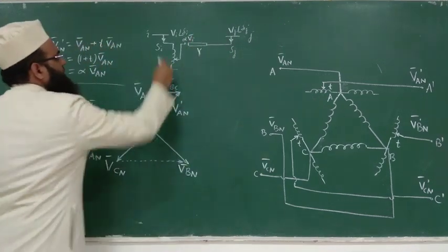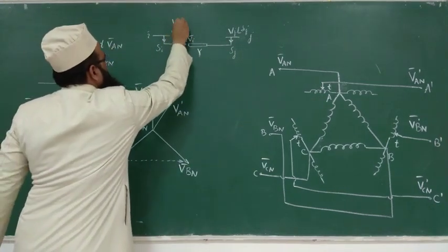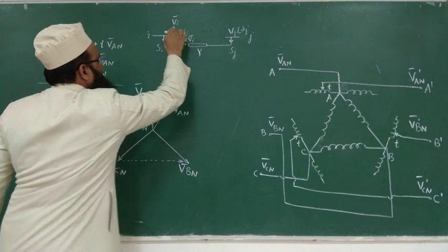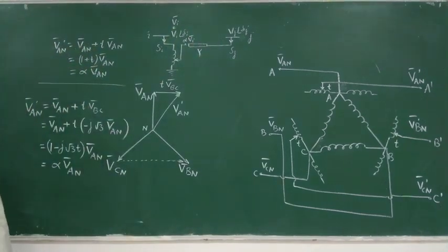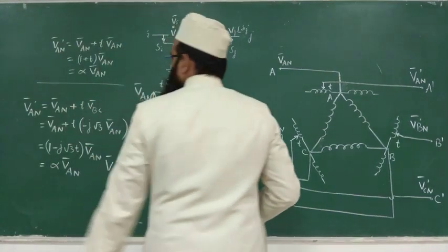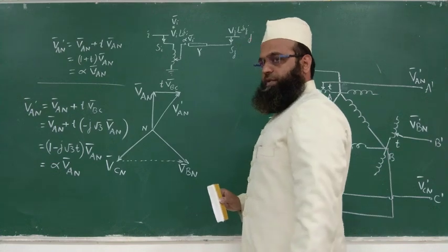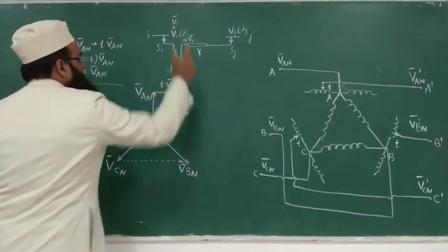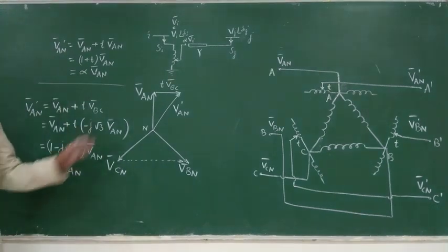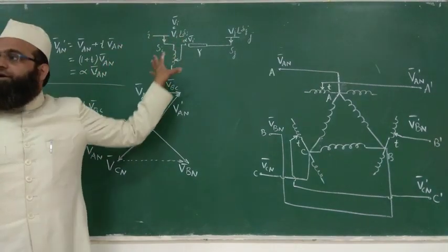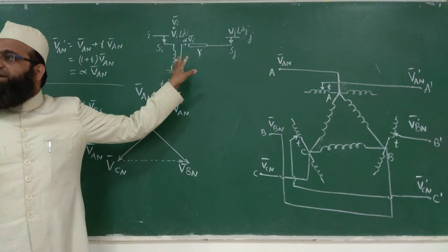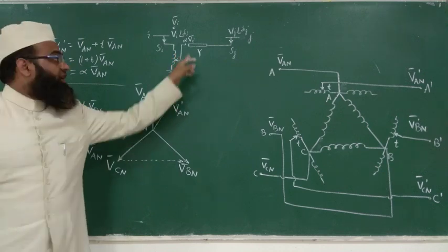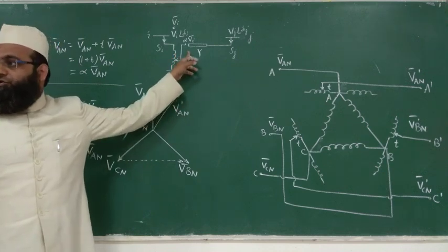I am writing phasor because this is nothing but the Vi phasor, Vi phasor is equal to this Vi angle delta, is it not? So this phasor has been changed now. Clear? Once this phasor has been changed, you need to construct a new bus admittance matrix because current will be changed here, is it not?